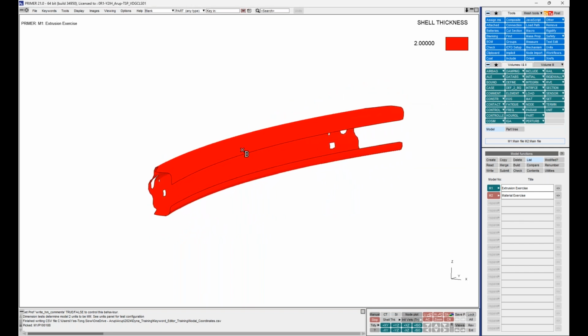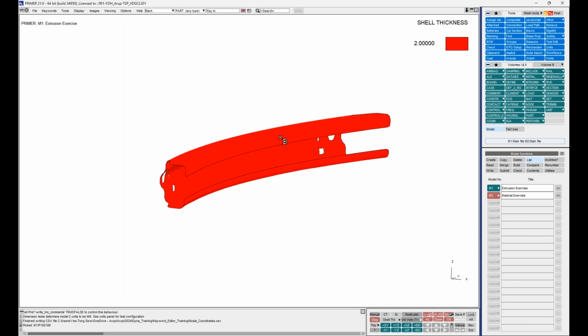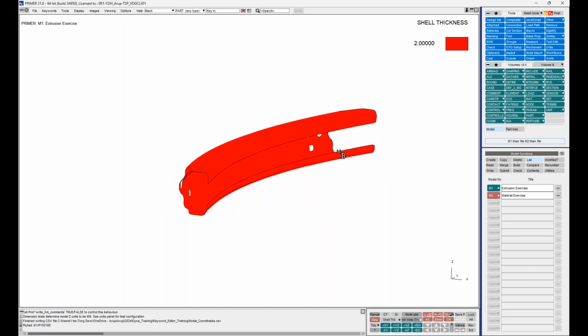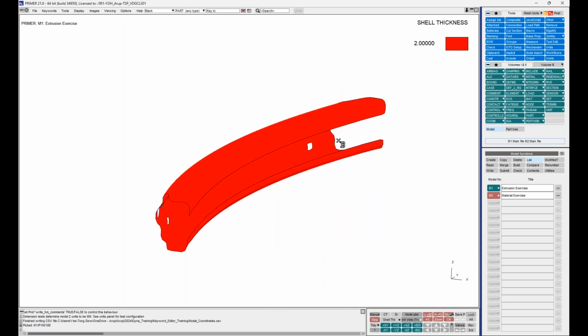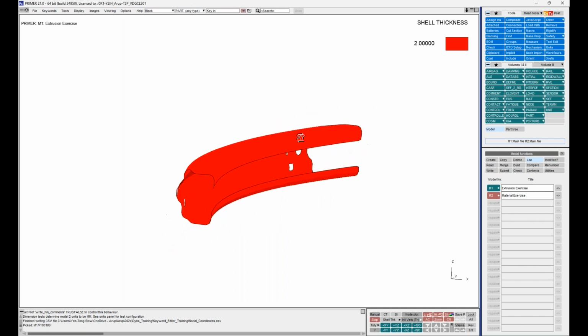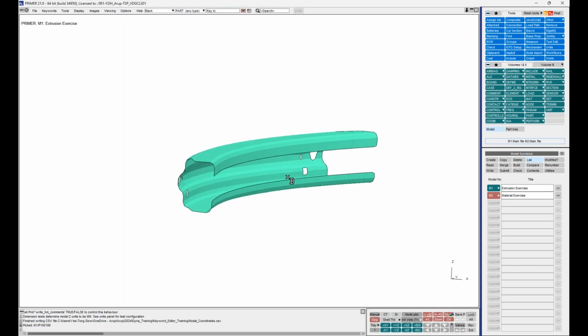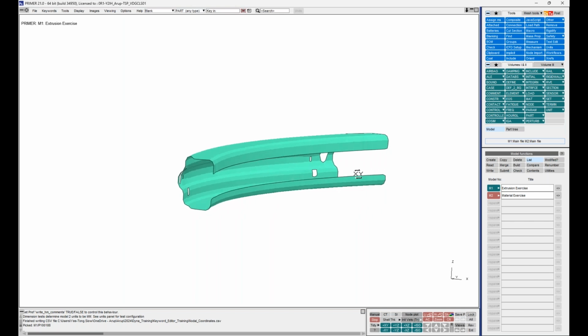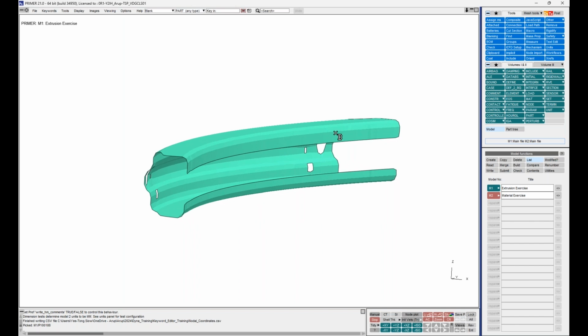So certain times, we might want the shell elements through one part to have different thicknesses. For example, in this case, maybe I want the back wall over here to be 3 mil instead of 2 mil. So what we can do as well is introduce thicknesses to the particular entities, so that this would trump the section ID card of your part, and it will only read the shell element thickness. So again, as a study right now, let's try to change all of these back wall elements to 3 mil instead of 2 mil. And we can use the keyword editor to do that efficiently.